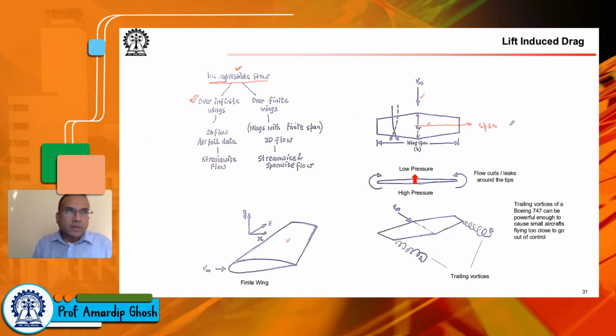So for these 2D wings, if you run an experiment where you somehow prevent the span-wise flow, one way to prevent it is to take a finite wing of a fixed cross section and put it in the wind tunnel so that the walls and the tips of that finite wing are flush mounted on each other. So there is no leakage flow. The moment you have that leakage from the lower surface to the upper surface, you have the finite wing effect.